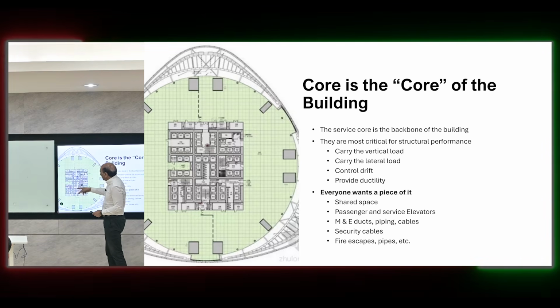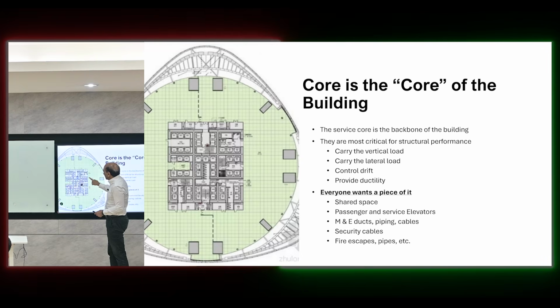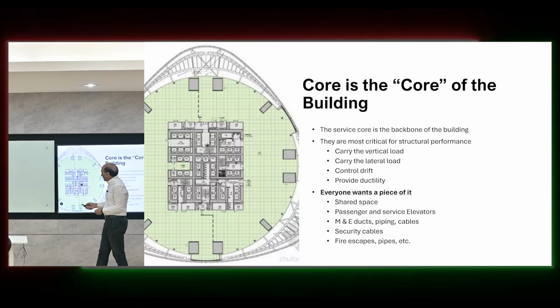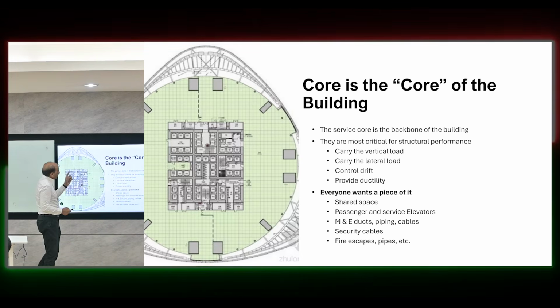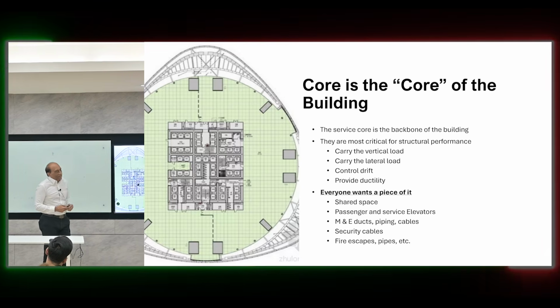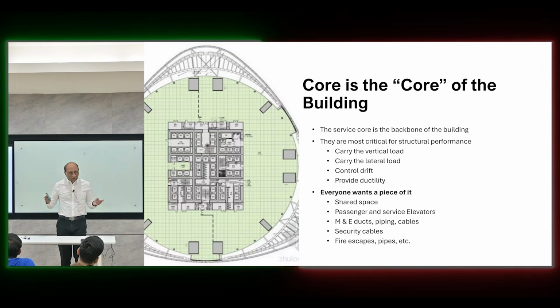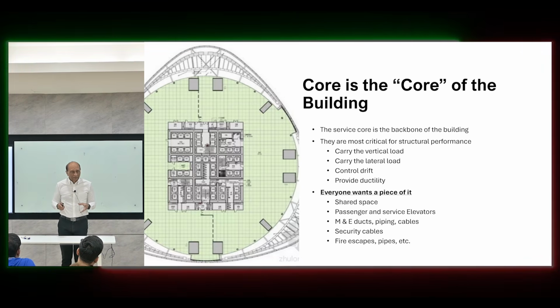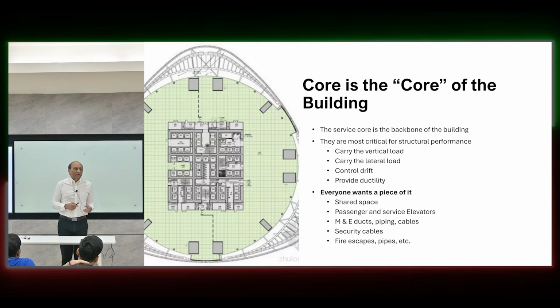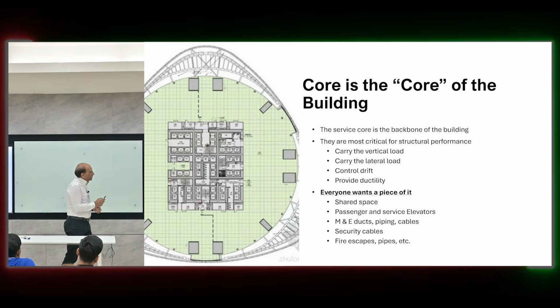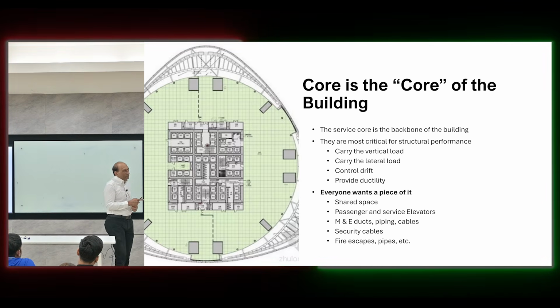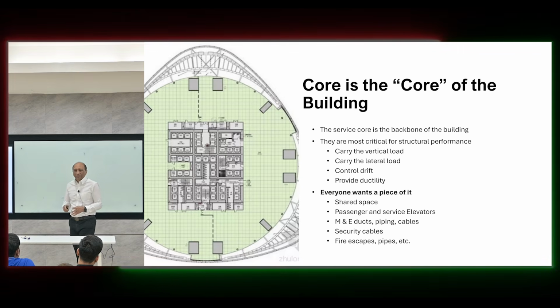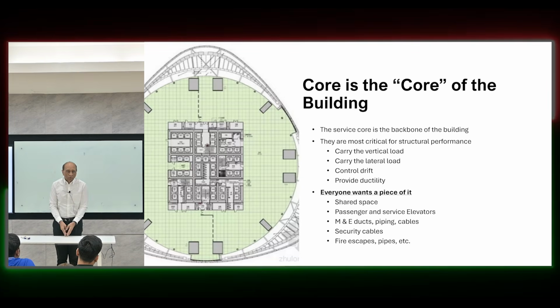There are elevators there, there's everything, and then very little space is finally left, and that is a challenge. Now, for the structural engineers, we carry the vertical load through the core because it's the center of the portion, and we also carry the lateral load. And that is one of the reasons that you will see many structural systems are trying to move the structure outside from the core to the outer side.